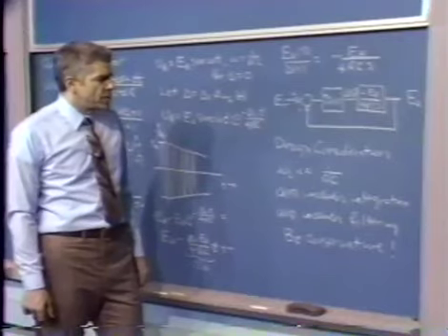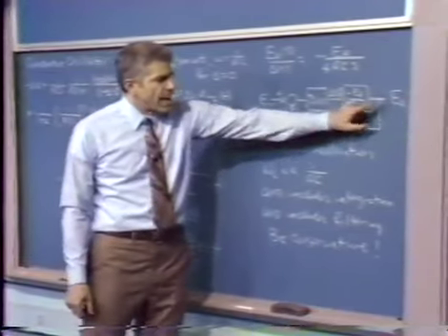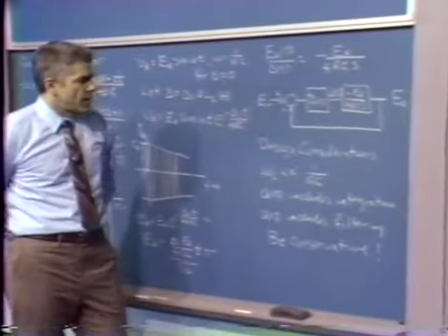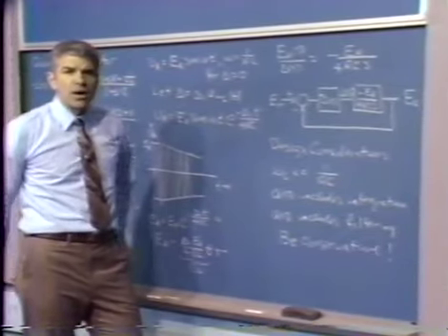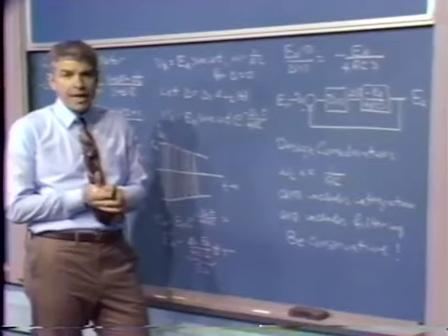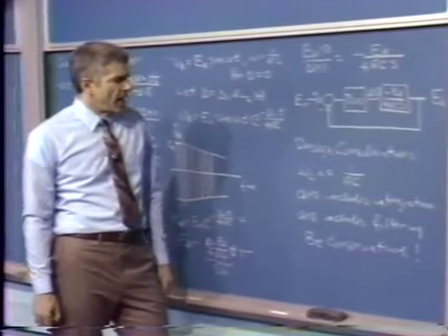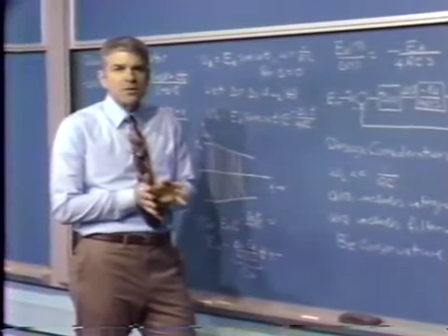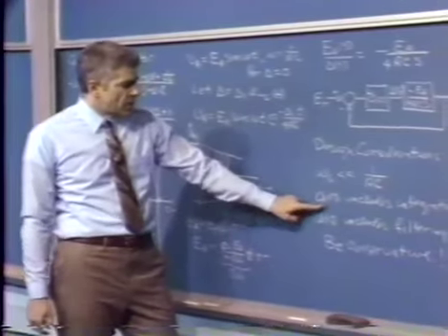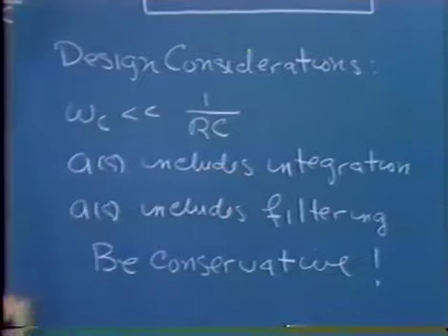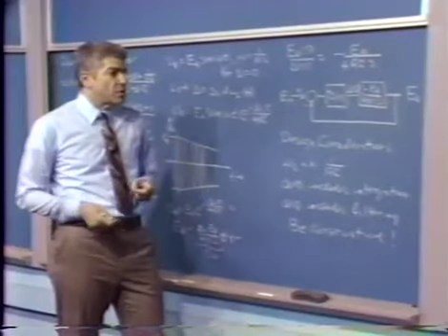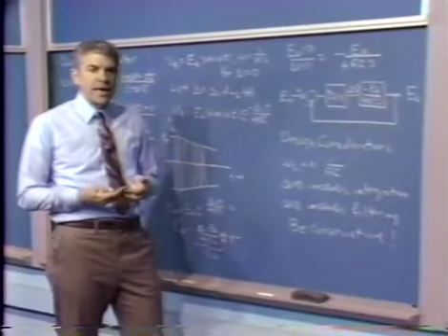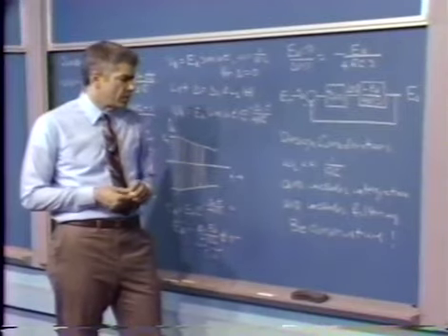We also might like to have a system that will force the output amplitude to be identically equal to the reference amplitude, and in general that requires some voltage, for example, on the control, the gate of our field effect transistor. And the way we can support a finite voltage with 0 error is to simply use an integrator. And so let's design our A of s to include an integration. That will ensure, as I say, that we can get any voltage we need to control the loop with negligible error, 0 error, between our commanded and actual value for the envelope.